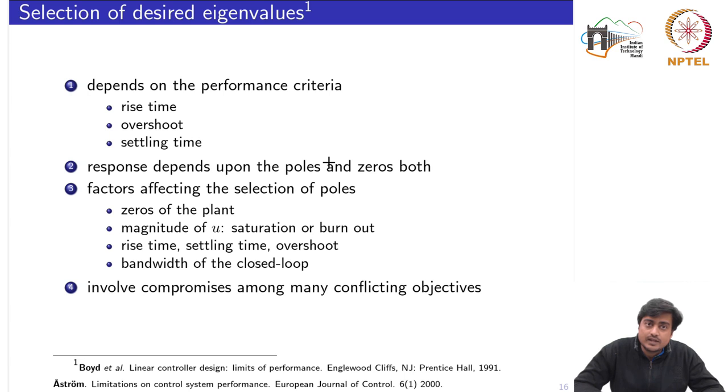In the last lecture we saw that if, by using the state feedback, you happen to place the poles at those locations where the zeros of the plant already are, then it may lead to the state of unobservability, which we will discuss in the coming weeks. So we need to take care that whatever poles we want to place for the closed loop should not overlap with the zeros.